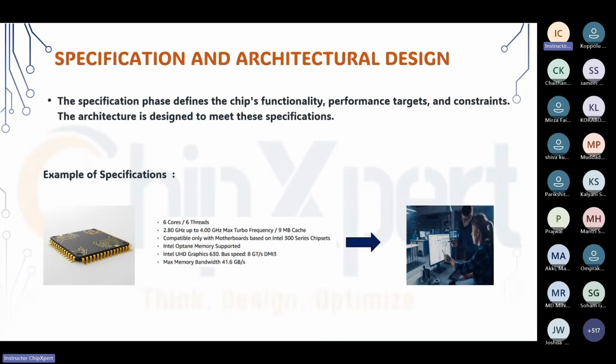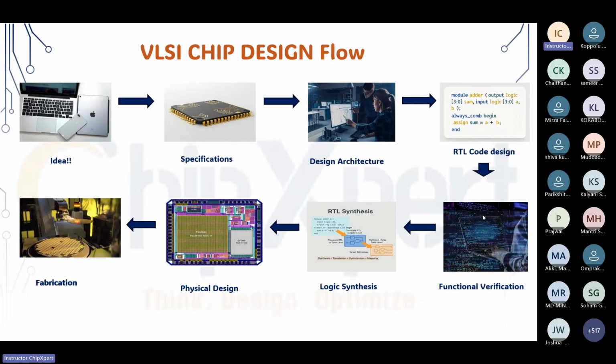Okay. So here functionally the RTL code is converted. That is, register transfer level is converted into real design code. That is a hardware language that will be validated by the design and verification people. Along with that, the logic synthesis team will synthesize the logic. Say 1 billion gate count is there, they will be optimizing it so that the area of the chip will be lesser and the power consumption is also lesser for each and every gate.